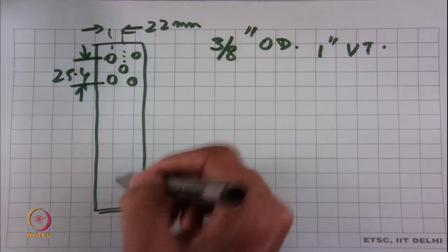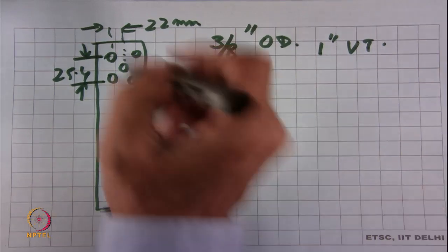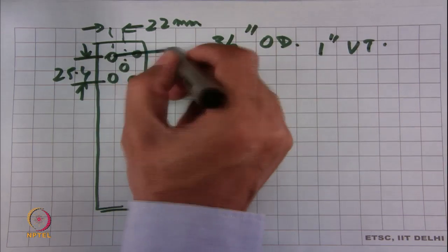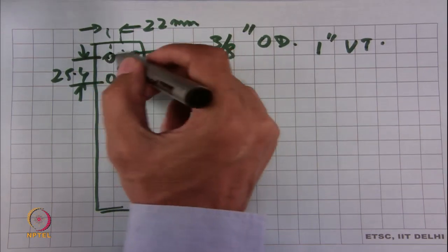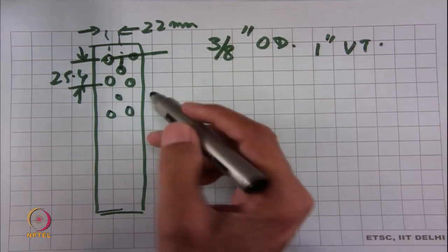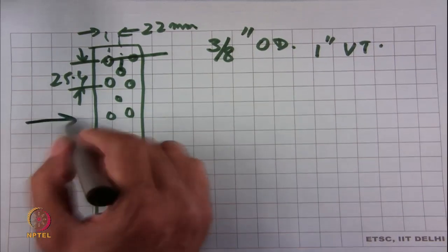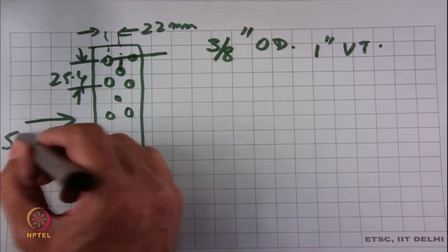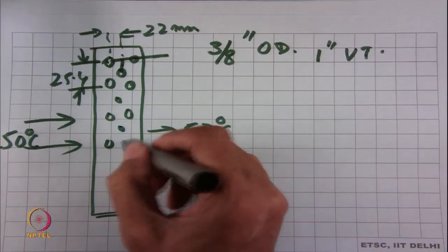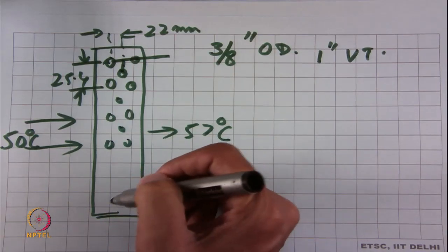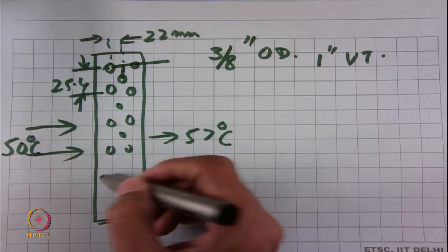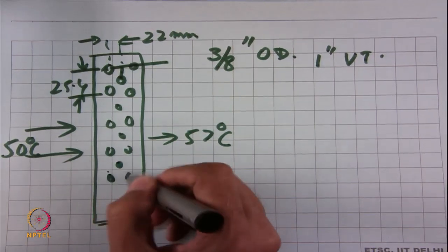types of coils. So, here we had discharge gas coming in on top. So, we make a header which feeds in these two and the central circuit, and we apply the same principle. So, in a condenser what is going to happen when you are doing testing, we are going to have hot air come in at 50 degrees centigrade and leave somewhere like 57 degrees centigrade. Again we need to balance the circuits, and here there was not any capillary available to adjust the flow. So, it was what it was, and there was a certain inefficiency which we knew would happen, but 3 circuits made this whole thing a little simpler.